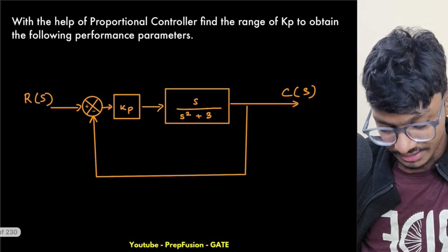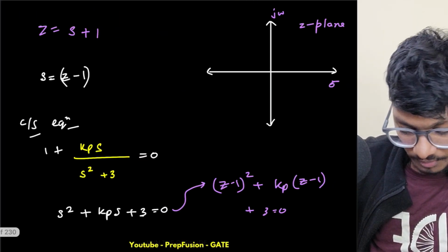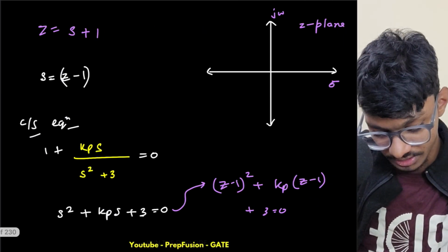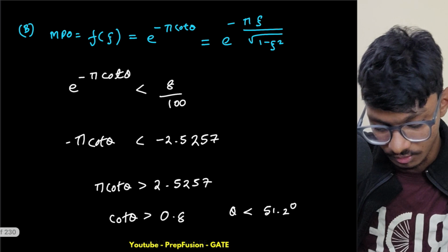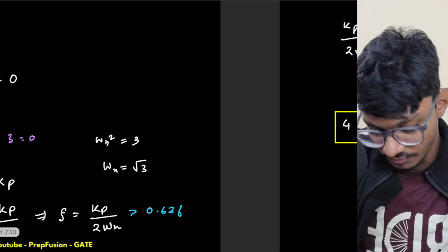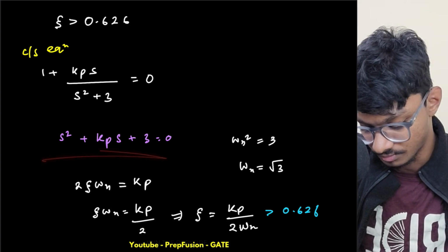So that's why this can trick sometimes. This root locus method can trick sometimes, because from here you can't know the behavior of the system. If you for some reason put Kp equals to 4 in this equation, and then calculate the value of zeta, it will come out to be more than 1. What will zeta come out to be?